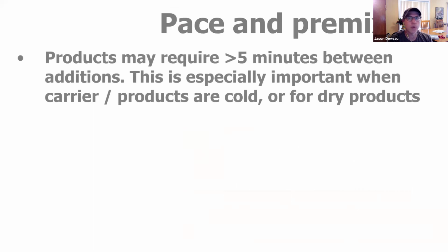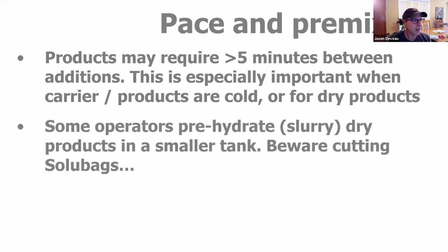Pace and pre-mixing, and we're doing well, by the way. We're getting near the end, my patient people. Pace and pre-mixing, they're important considerations. Some products, particularly the dry products, can take as long as 5 minutes to be truly hydrated and dispersed. And that's particularly important when your water's cold. You saw that earlier. So, the rule of thumb is if you think it's dissolved, even if it looks dissolved, probably isn't.